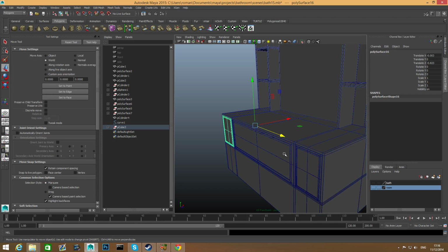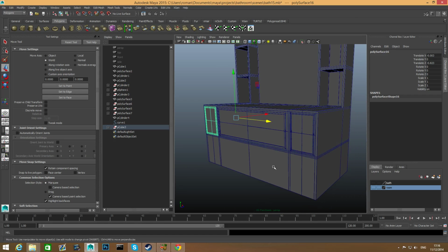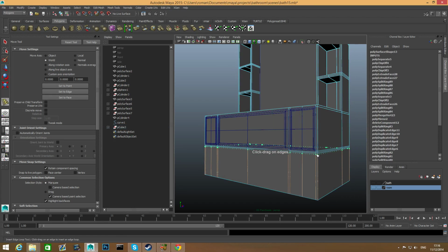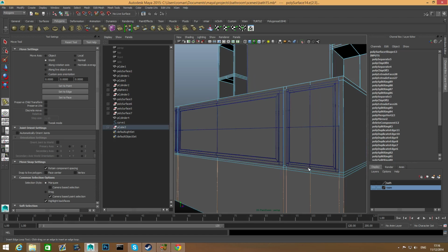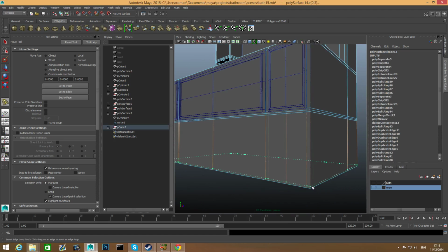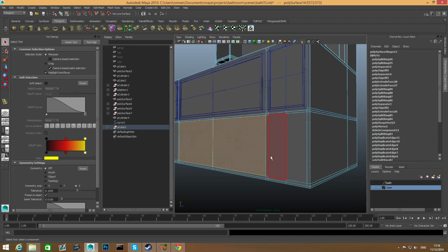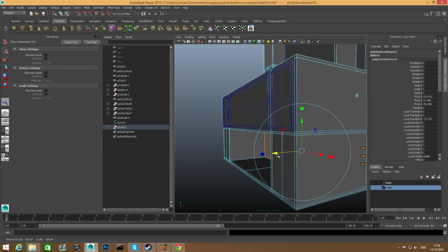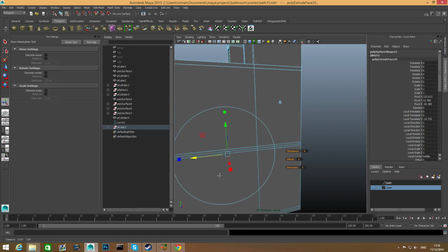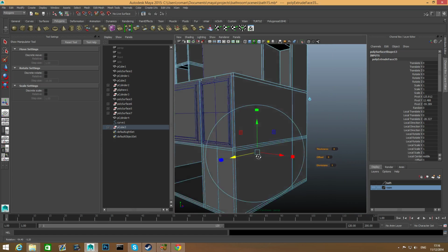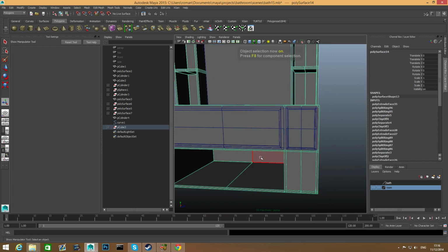these two there. Now we'll grab this, shift right click, insert edge loop. I'm going to add one edge loop. Well, I think I do have this edge loop over there. Yeah, I have it. So I will simply add 1 or 2 edge loops here, and then I will be able to take this and extrude it inside. Okay. So now we have a big shelf that we can put, I don't know, whatever you have in your bathroom. Press F8 to bring it back to object mode.